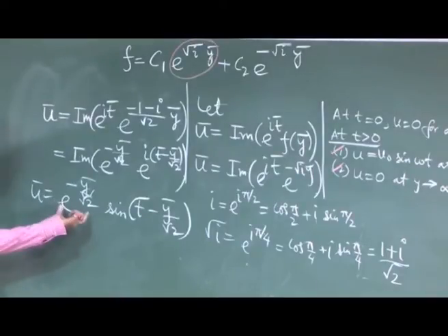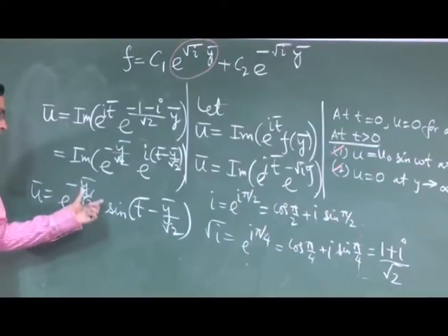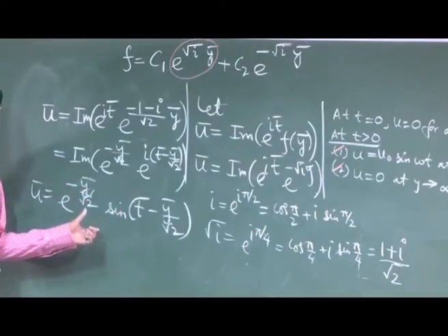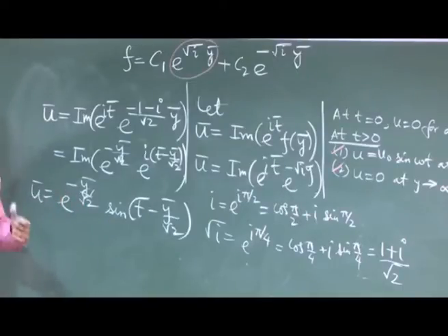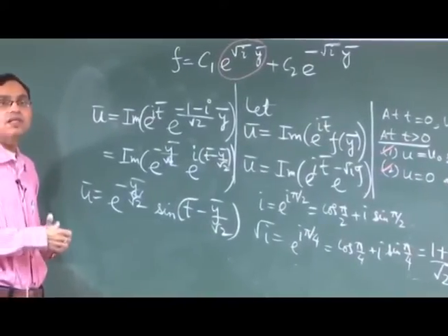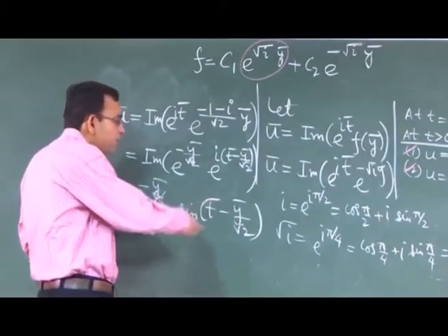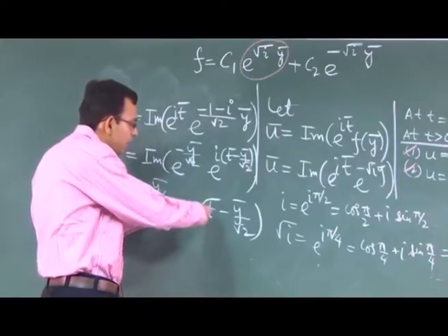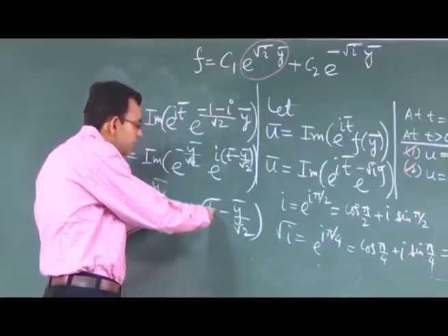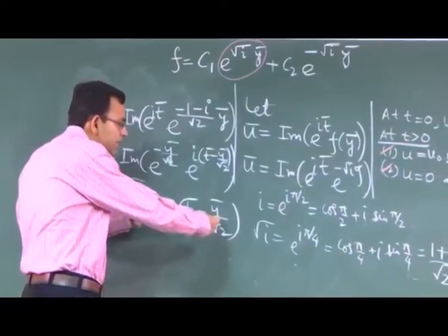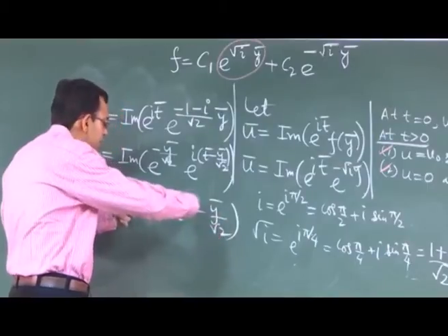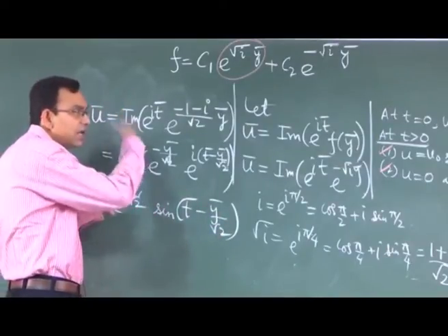So, you can see there is an exponentially decaying part which actually spoils the harmonic nature of the solution. So, it appears to be a wave propagation problem, but it is not actually a wave propagation problem, because there is viscous damping, and then you have this damped oscillation type of characteristic where you have a wave nature which is a combined effect of space and time. So, it is a spatiotemporal propagation along with an exponential decay of the function.